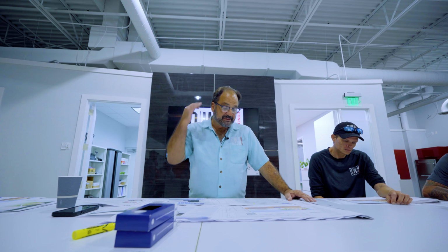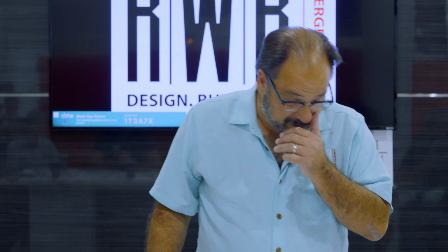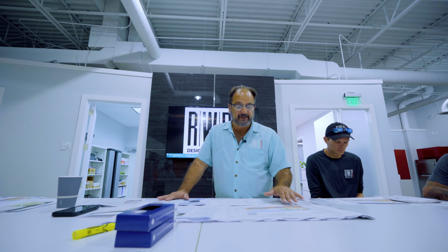Okay? As a rule, you're not supposed to have more than 6 inches on top. There's supposed to be a certain amount in the bottom. Even if you're on the ocean and you have beach sand, that doesn't mean the sand is appropriate for a septic. Okay? In almost every case, they'll grade out the sand that's there and they'll put in clean sand that fits the septic design. Okay? So this is the concept of how a septic works.